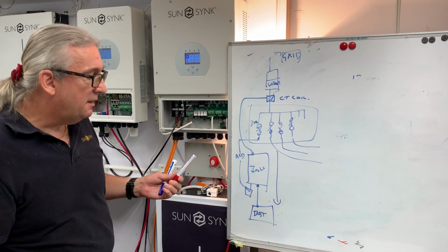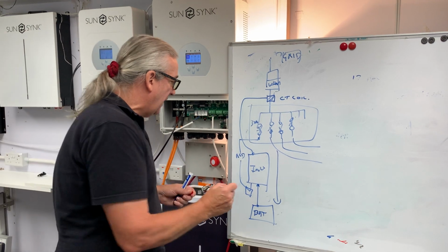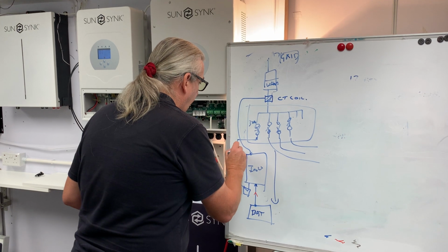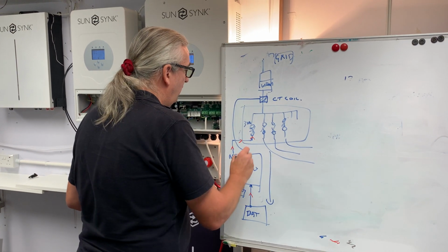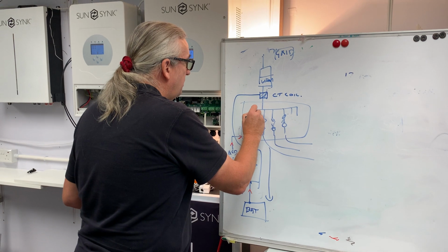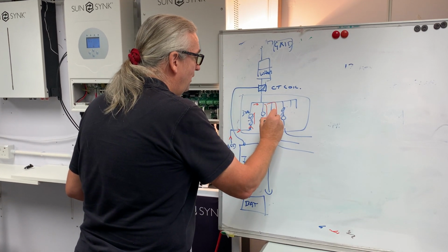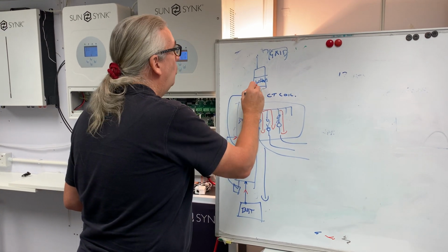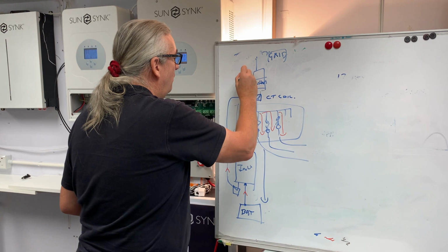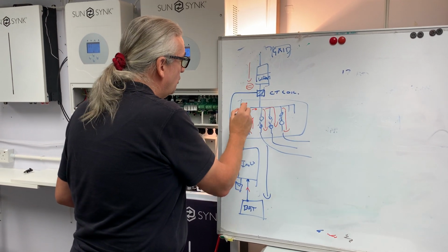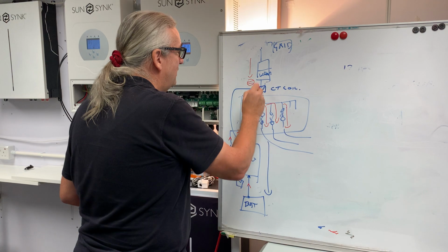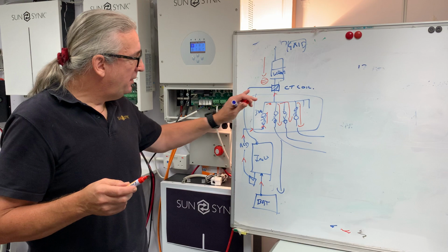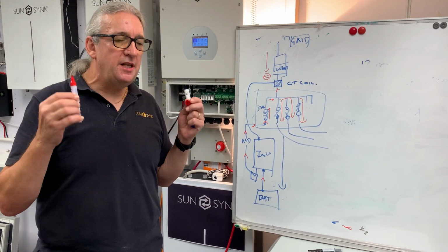During the evening it charges the battery, and at night time, or when we're using the power, maybe even in the early mornings, when it's not charging, the battery reverses and starts flowing back. The power flows through the consumer unit onto the bus bar, and it flows back out into all your things. And the CT coil here, this is the magic, will stop any flow coming this way. The cable's physically connected, but by controlling the energy, we block it.